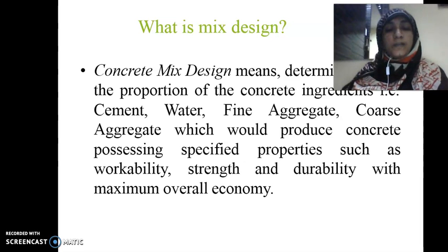Workability, strength, and durability are the aims and goals of our design. To determine the proportion of ingredients of concrete which would produce workability, strength, and durability with maximum overall economy is called concrete mix design.